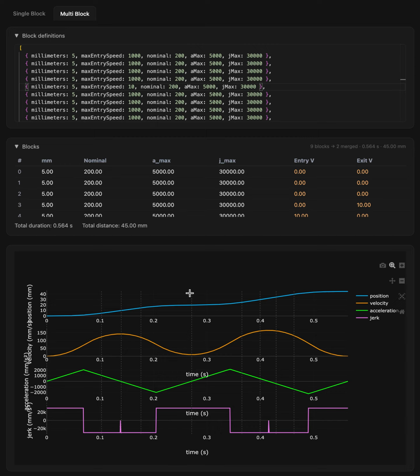Now, this introduces some extra problems, of course, which are that FTMotion is going to have to execute a single trajectory that goes across multiple blocks. But I don't think it's going to be a problem because while FTMotion is generating the trajectory points, it knows how much distance it traveled, so it can understand that even though it's calculating a single trajectory, it crossed a block boundary, and then it can load the next block. So the rest of Marlin knows which proportions to move each axis to that block. So this should hopefully work fine still.